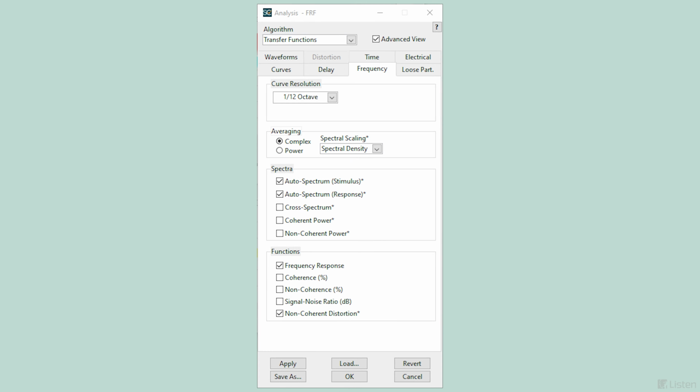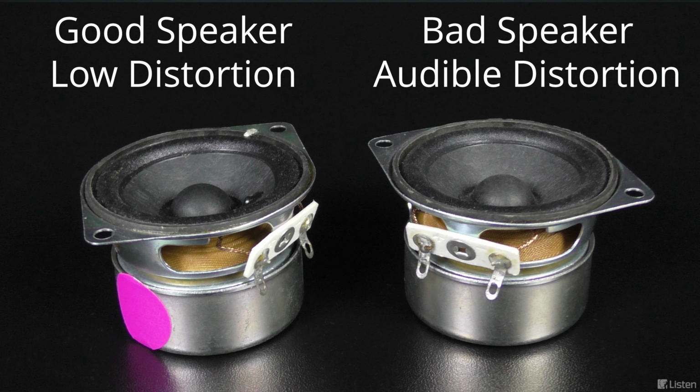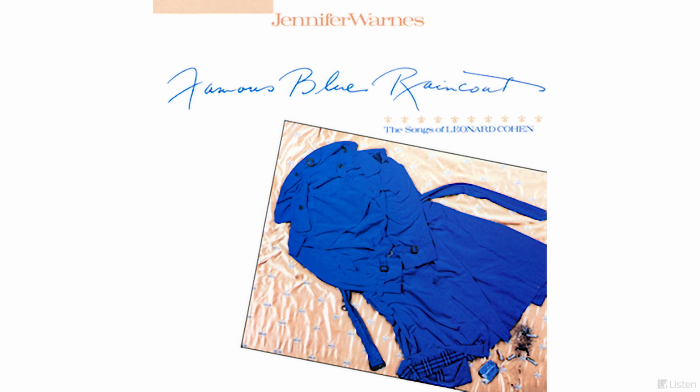Configuring non-coherent distortion in SoundCheck is a simple checkbox in the transfer function analysis editor. I have a good speaker and a speaker that exhibits some fairly significant distortion. Let's look at the good speaker first. I'm going to play a short excerpt of Bird on a Wire at 90 dB SPL by Jennifer Warnes. This song is widely used as a test track as it has good dynamic range.